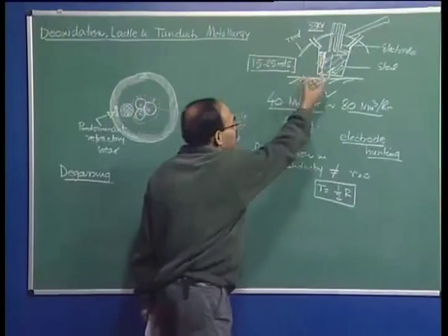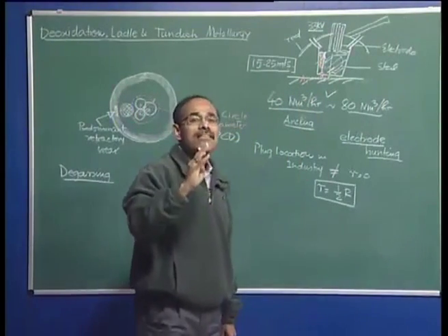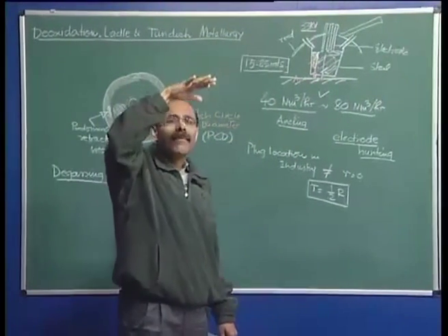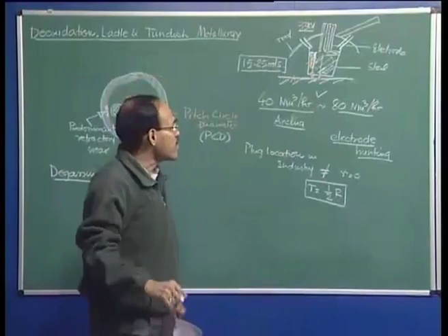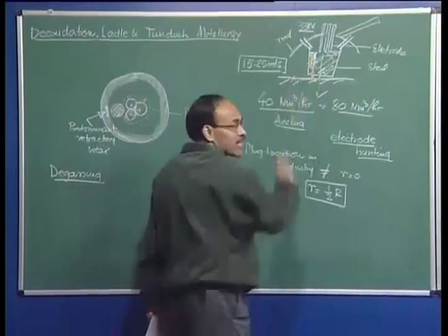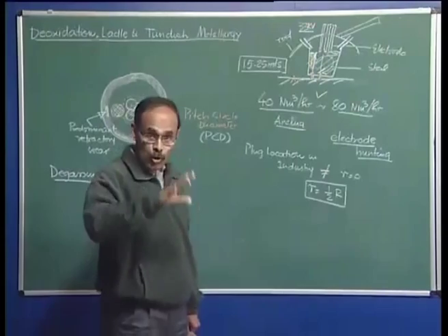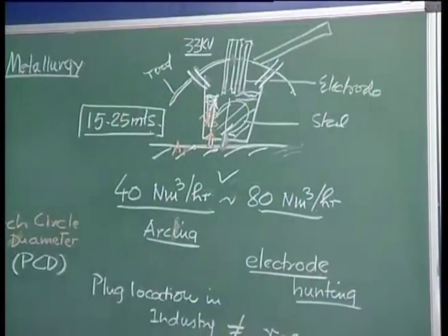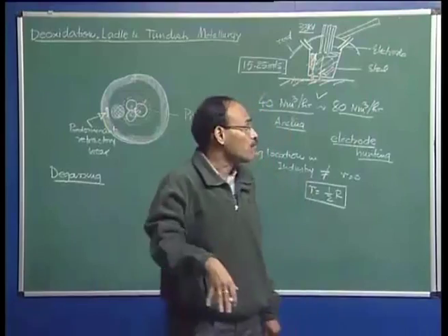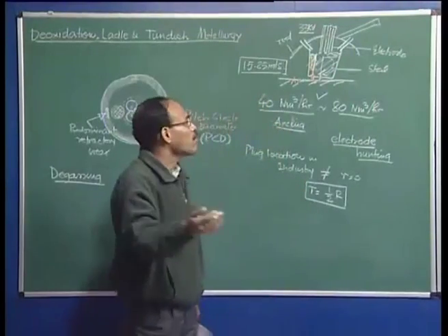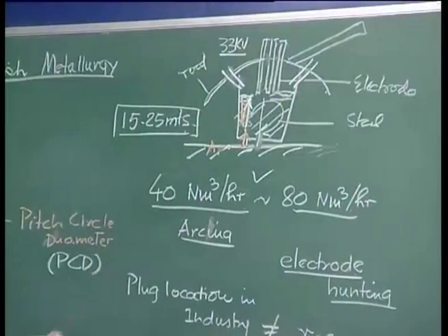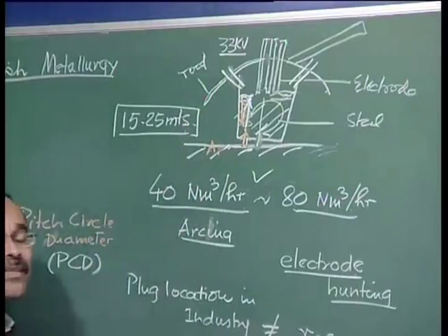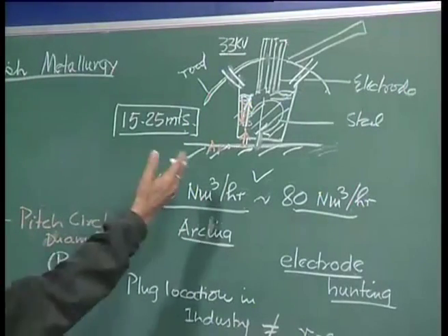So, when you get the material out of the ladle furnace, it has a little bit more temperature than is desired at the casting station. Its composition is correct in terms of solutes, but it may still contain nitrogen which may have been absorbed during tapping of the furnace itself, hydrogen which may have been absorbed because of some wet material, like for example, the lime that we have added to make the slag.